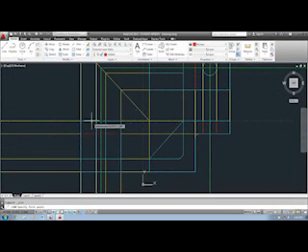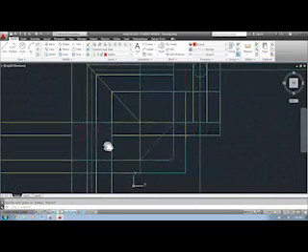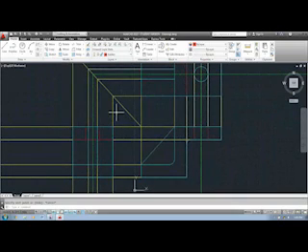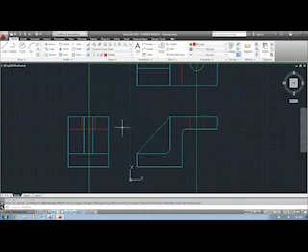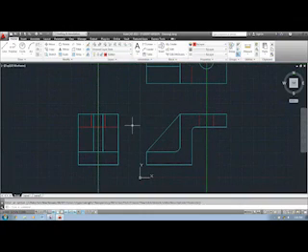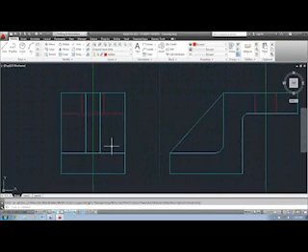So let's see, I'm just going to come out in this direction. Total of 7.5 units. Come down. Same thing over here. And come down. Okay, so almost done. In order to reduce the clutter, I'm going to turn off my construction layer by clicking on the light bulb. Okay, that way all those yellow lines are gone. Well, they're still there, you just can't see them. It's handy if you're having to clean something up.